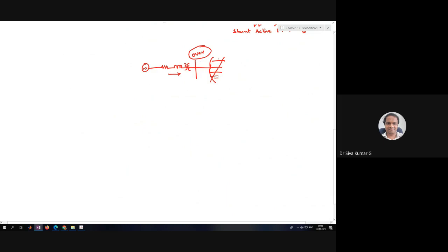Whenever you switch off the loads and you have capacitor banks connected over here, because of that reason also we experience the over voltage. But in this case, the over voltage is not because of a fault, it is all because of the loads. Even when you connect huge capacitor banks over here, suppose the number of capacitor banks connected at this particular point is more.